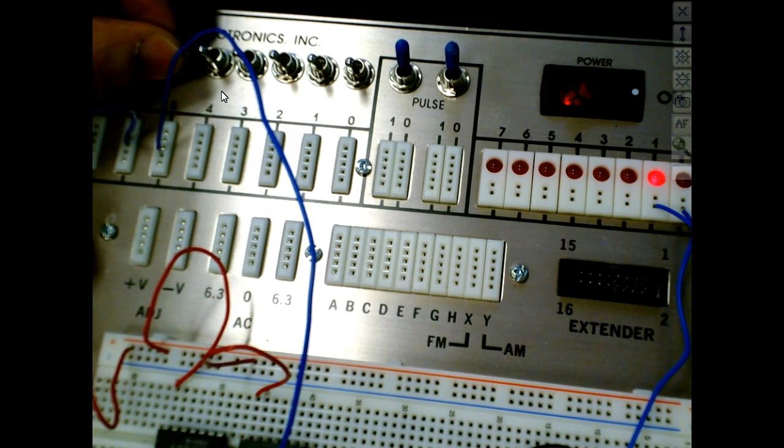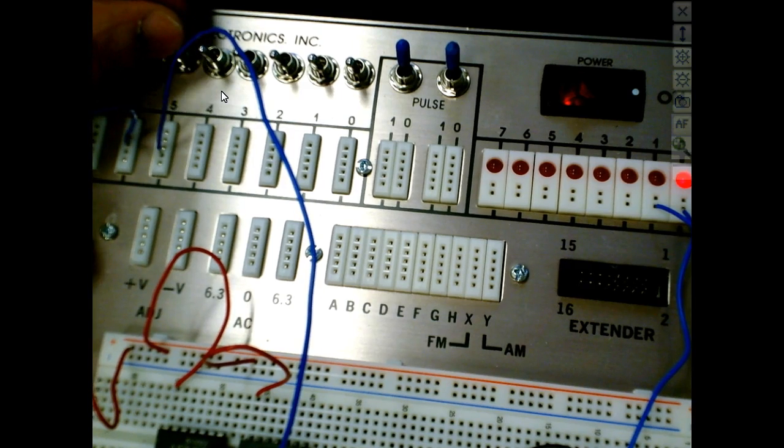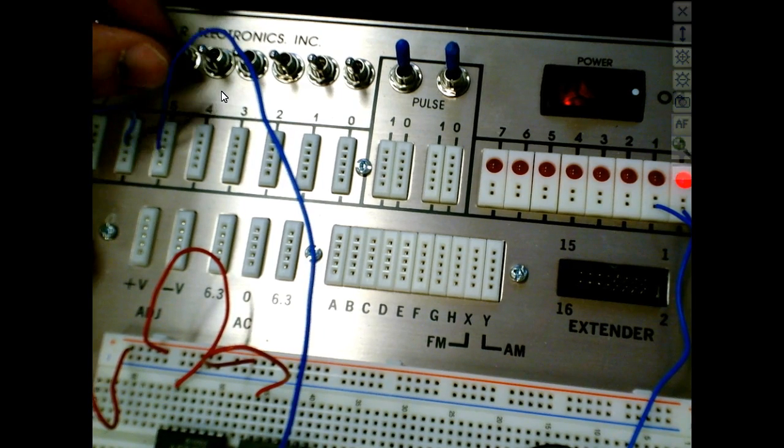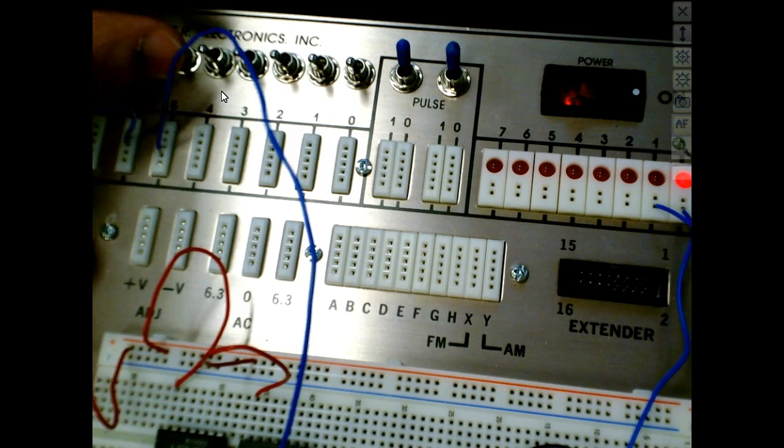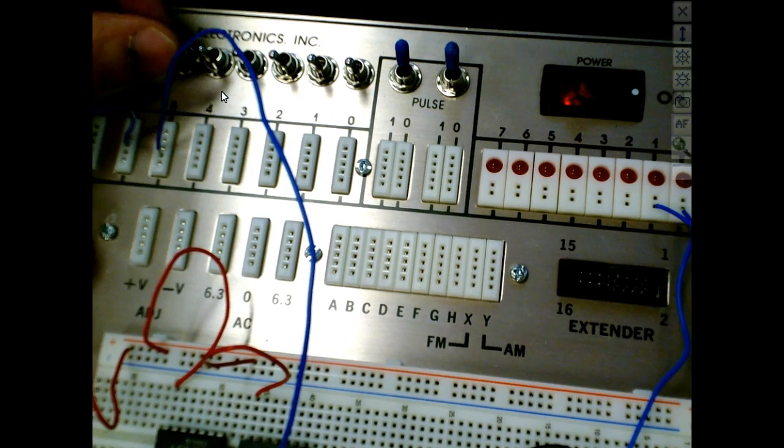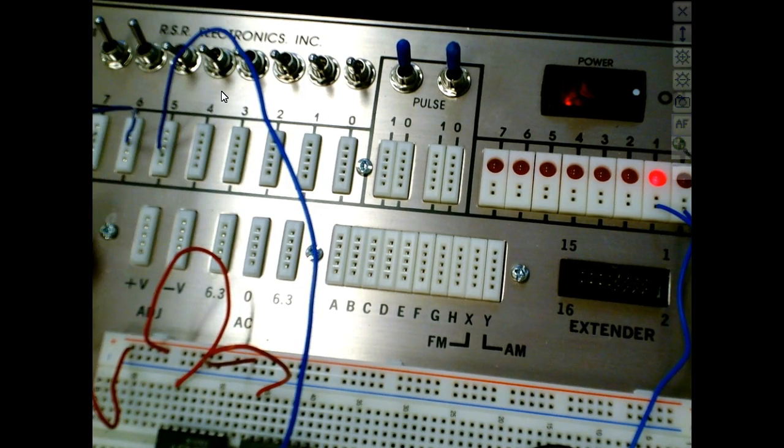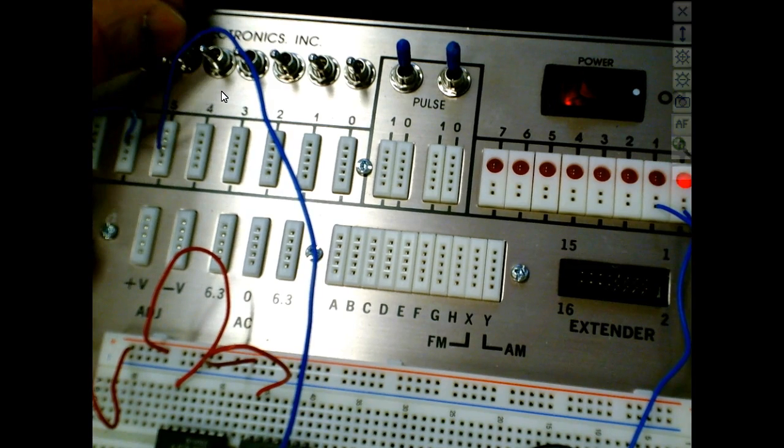Oh, came up set that time. Came up reset that time. Came up reset that time. Came up reset that time. Oh, came up set that time. I flipped it off. So see, now it came up set. So that's why if we put 2 1s, they call that an ambiguous state. Now, why do they call it an ambiguous state? Because there's no guarantee how it's going to come up when you bring it out of that state, right? So all I'm doing is flipping the enable.